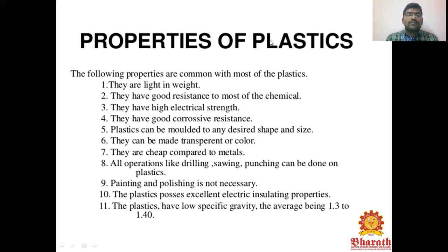All operations like drilling, welding, and punching can be done on the plastics. Painting and polishing are not necessary for the plastic material. The plastics possess excellent electrical insulating properties. The plastics have low specific gravity. They average 1.3 to 1.4 for the specific gravity of this plastic material.